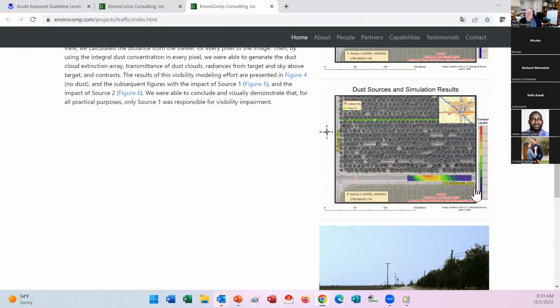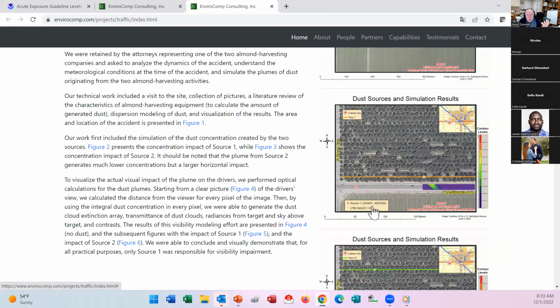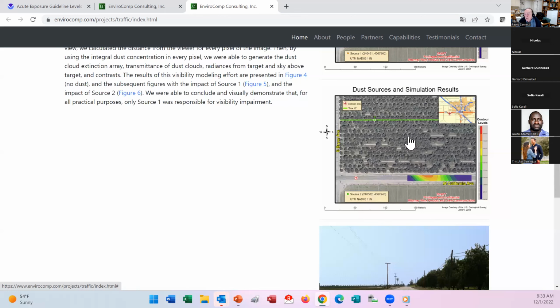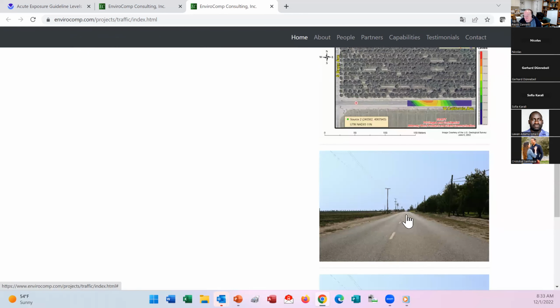And then we have the plume here that was calculated using, I think, AERMOD or ISC. We use a Gaussian plume model. So each pixel has a plume going through. You see, the observer is here at the end of the street, looking in this direction. This pixel here should contain the impact of the entire plume. How do we do that?